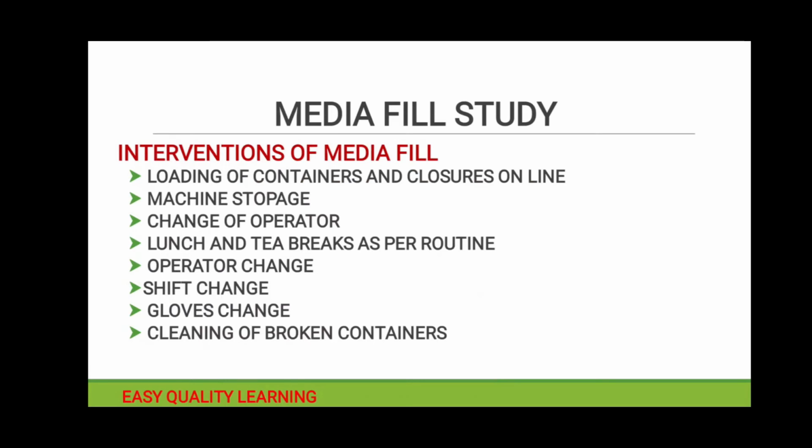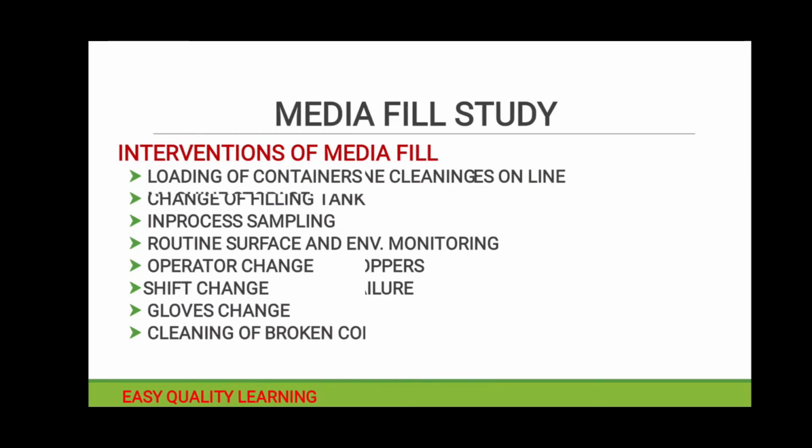Then we need to clean the broken containers, and then our line will restart. So that needs to be simulated: if our container breaks in between, whatever activities we do as per our SOP, the same shall be simulated during your media fill activity.